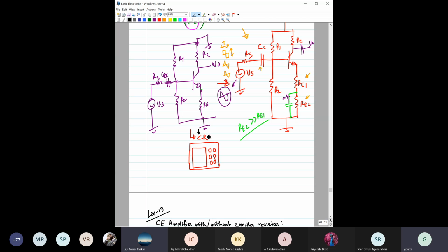Oh, okay, sir. But an oscilloscope can be of different types. This is a cathode ray type, meaning you have an electron source. Then you apply the signal across the horizontal and vertical deflecting plates, and there is a fluorescent screen here. You move the beam and the fluorescent screen will glow. That's how you can see the signal in this type of CRO.